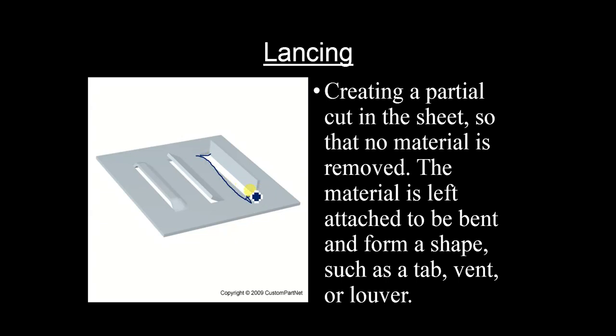Clear? And we are bending the sheet at 90 degrees over here. Then we are creating one, two and three cuts over here, and we are creating a bend in this way. Clear? And this is another cutting process. We are creating a slit over here, and we are applying certain force from the bottom, and you see that this metal comes out in this way.